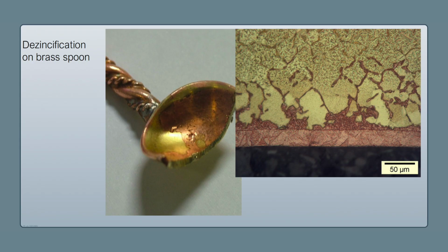This also leads into another type of failure that I've come across throughout my work with Mintek. It's this dezincification and selective leaching. Again, we have a solid solution alloy. Here we have a decorative spoon that was manufactured by our artisan training division probably 10 years ago at Mintek, and they wanted to clean the spoon to do some changes. And then in the end, the solution they used caused this dezincification or dealloying, which is the selective leaching of the zinc out of the brass.